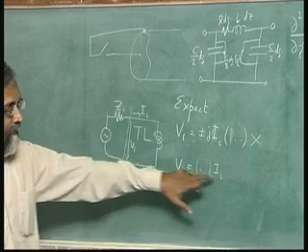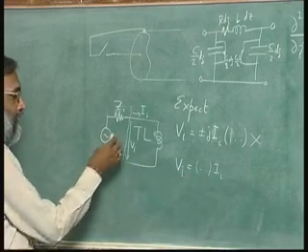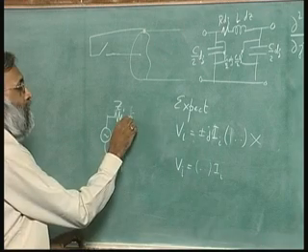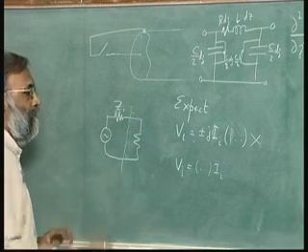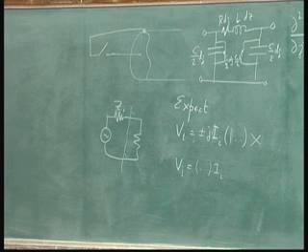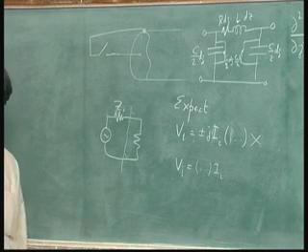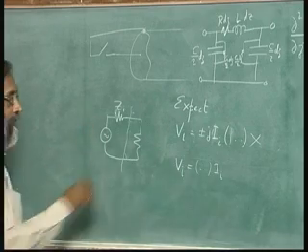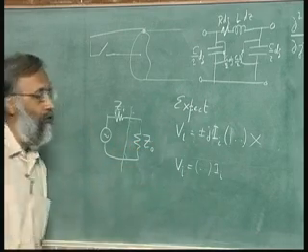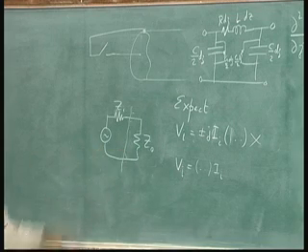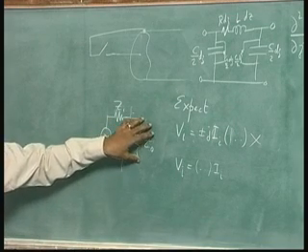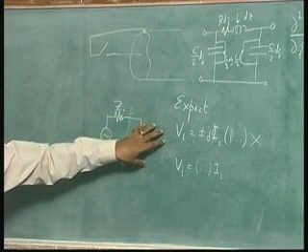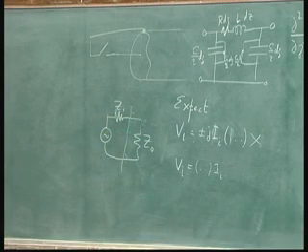That is, the voltage and the current will be in phase, and this transmission line will look like a resistor. And the theory of transmission lines starts with this, namely that there is a characteristic impedance to a transmission line. It is a real number, which means it looks like a resistance, and your source must drive this characteristic impedance of the transmission line.